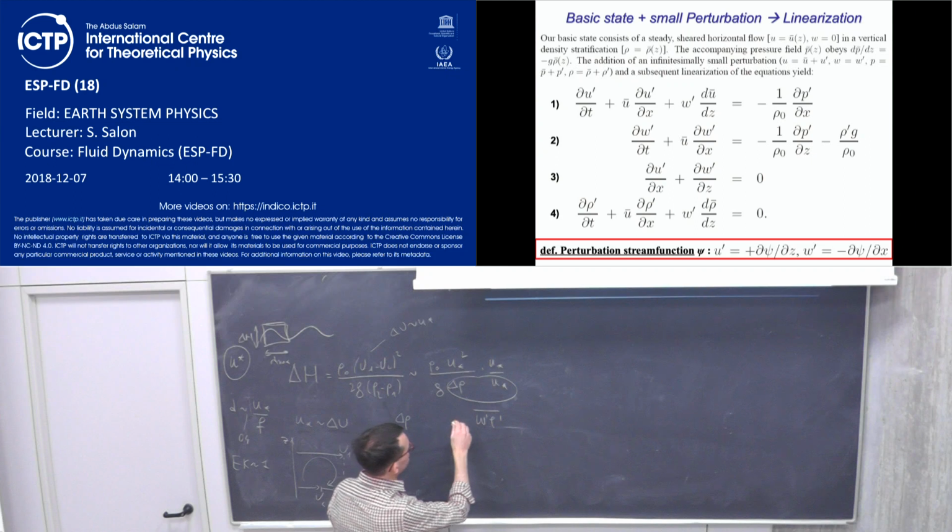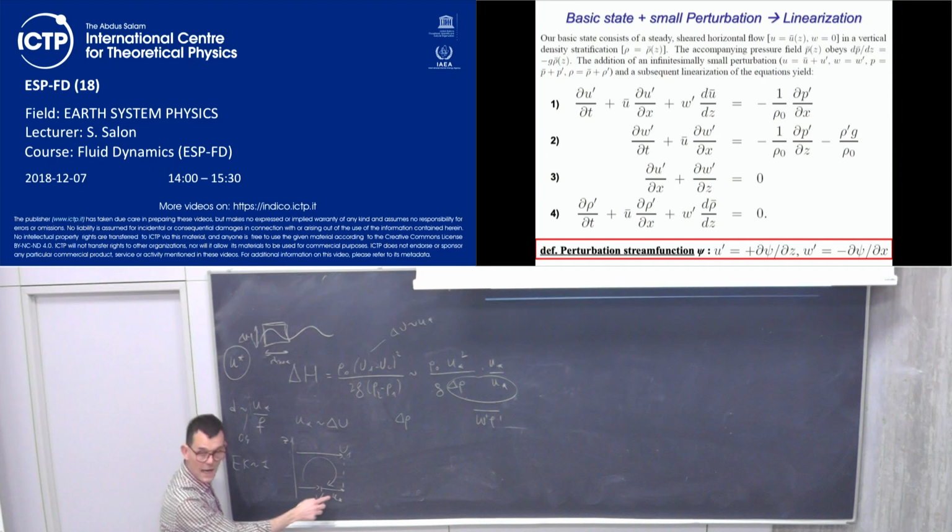So I'm saying that the multiplication of a friction velocity, which actually is in this direction, but actually corresponds to the velocity of, let's say, this eddy, okay? This is an eddy, okay? It's a typical system that you can have in a stratified system, okay? So I had said that U star is the scale of the variation of velocity, but U star actually is the scale of velocity of an eddy which is living in the stratified system.